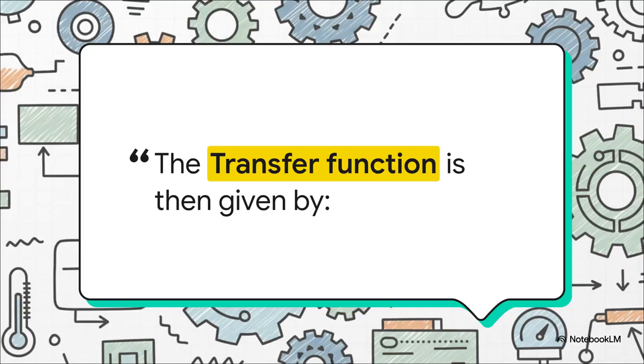And that whole process gives us this final transfer function. X of s over F of s equals 1 over the quantity of mass times s squared plus damping times s plus the spring constant. I really want to stress this point. This equation is the block. It represents the total, real-world physical behavior of our mass, spring, and damper. But now it's in a format that our PID controller equation can plug directly into.